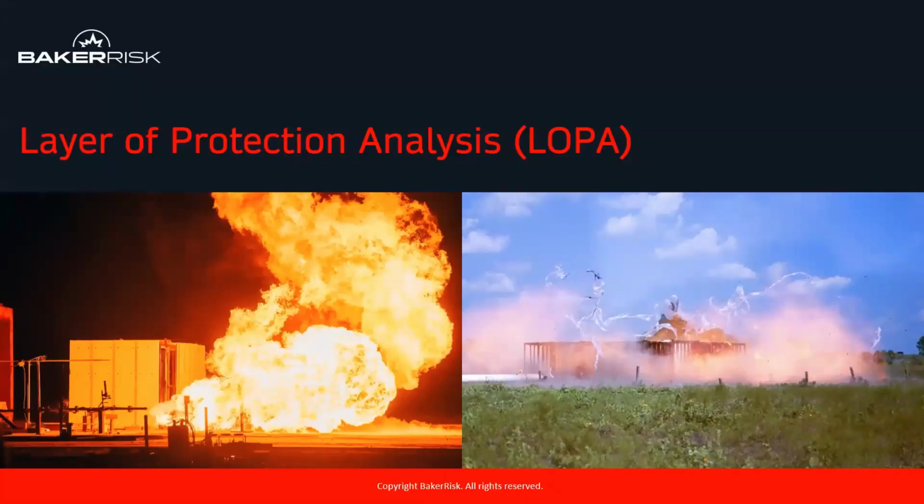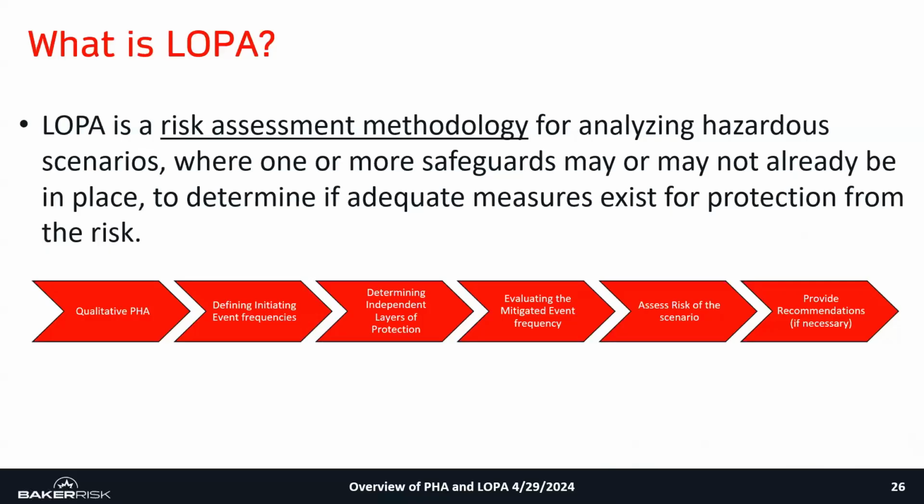So moving on to the subject of LOPA. What is LOPA? LOPA is a risk assessment methodology for assessing hazardous scenarios where one or more safeguards may or may not already be in place. And it's a tool used to determine if you have adequate protection. So is your risk tolerable?